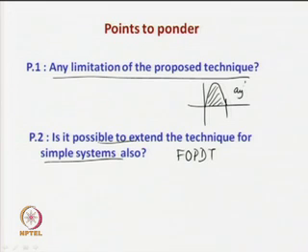So, A y dash, and similarly area of half period of the input signal A u dash, and the ratio of the two will give you the steady state gain. That is particularly for first order plus dead time systems, whereas this technique may not be applicable for large order systems or systems with higher dynamics.